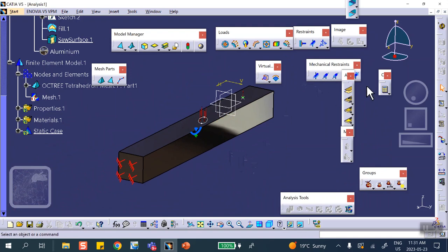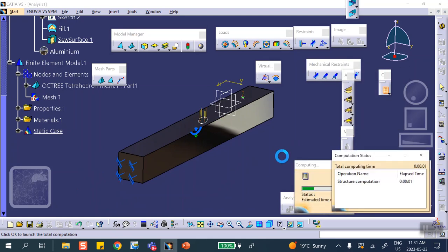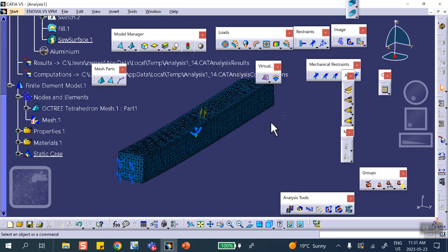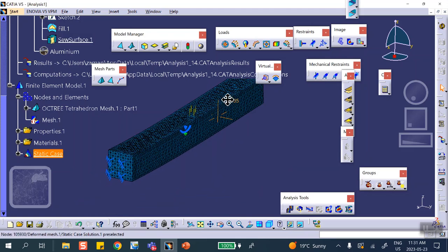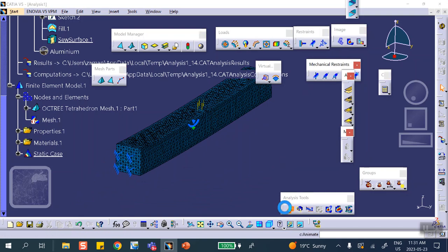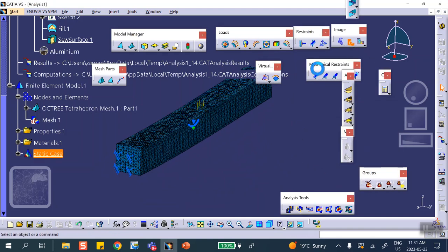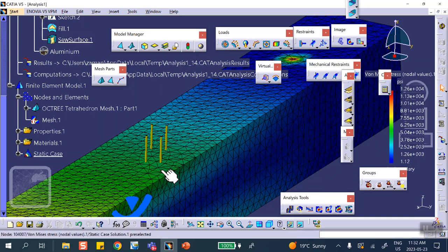Okay, so let's run it. It's going to be fast. Good. You can look at the deflection. Now, depending on what the pressure was, what the area was, and what the force was here, it may be going up or down. I don't know. This force is a lot bigger than that force imposed by the pressure. That's why it's going up. If you look at the stress right there, you can see that there's a big force here. That's why it shows. And there must be a stress distribution here.